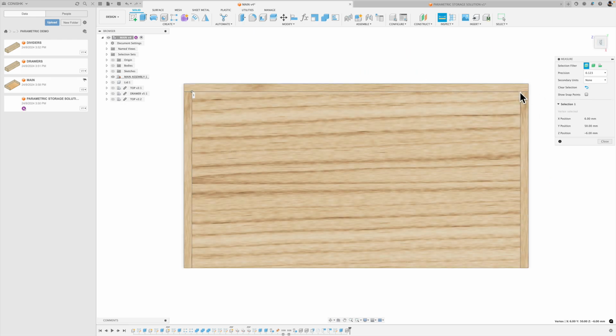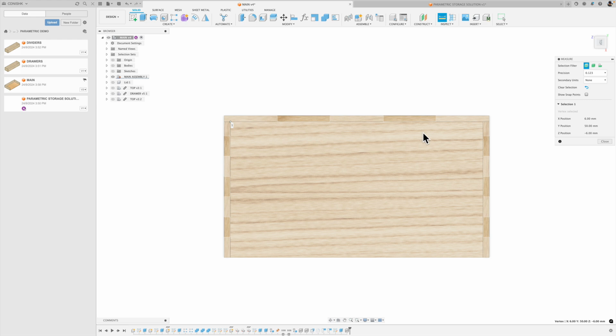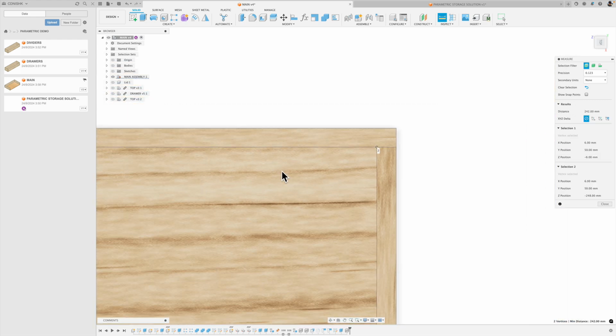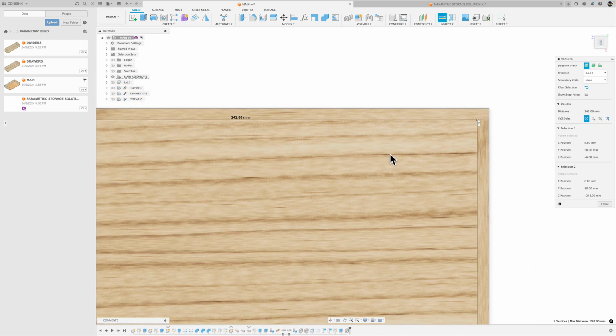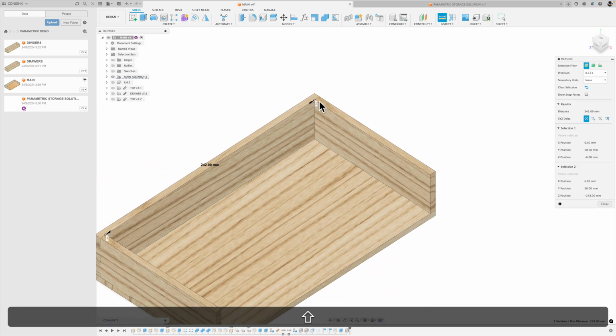Again, you would look at your physical prototype for guidance on the measurements that you will need. In this case, I am taking measurements from an existing CAD design, and I'm zooming in here just to make sure I have precise snapping of the measure tool to get that internal dimension. So I'm writing the internal dimension down on a sticky note here off screen, and we have a dimension now, of course, for that part of the model.